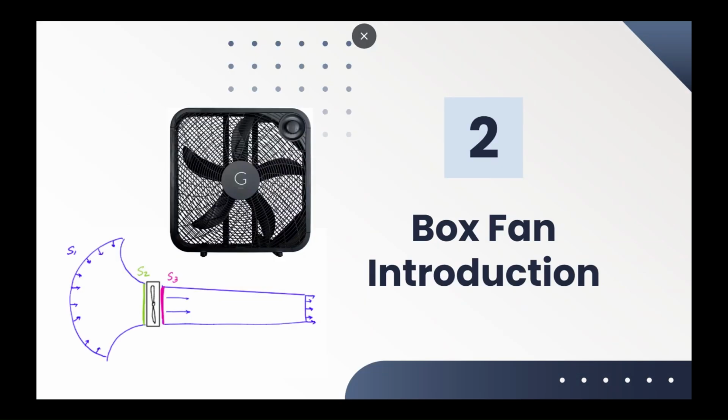Just as we would treat helicopter propellers, wind turbines, and other unshrouded axial flow pumps, we analyzed our box fan as a set of rotating airfoils which uses rotational motion either to imbue or extract energy from the air around it. To better understand our fan, we analyzed it as a thin disc actuator and used measurements of wind speed before and after the box fan, as well as an analysis of the airfoil pitch angles and rotation rates of the system to better understand the ideal working conditions of the fan and potential design improvements that could be made.